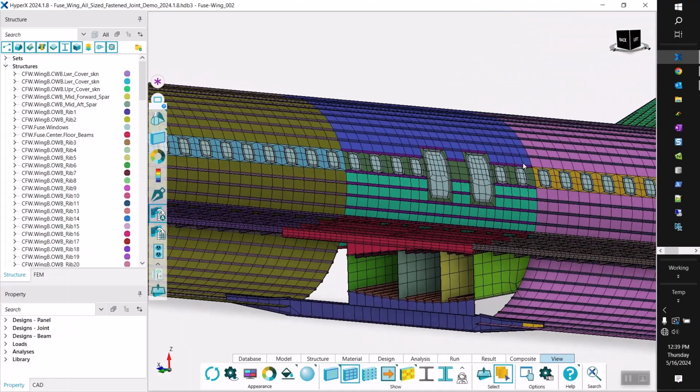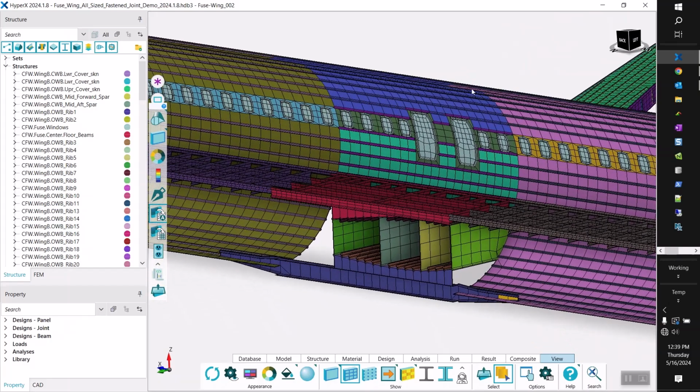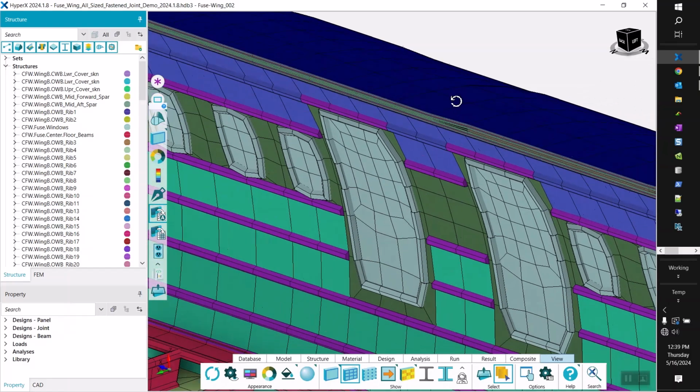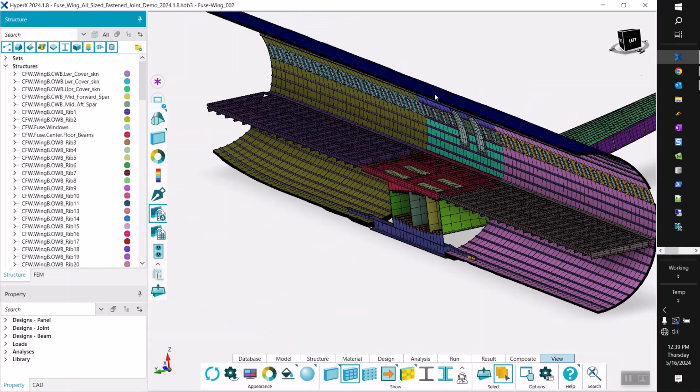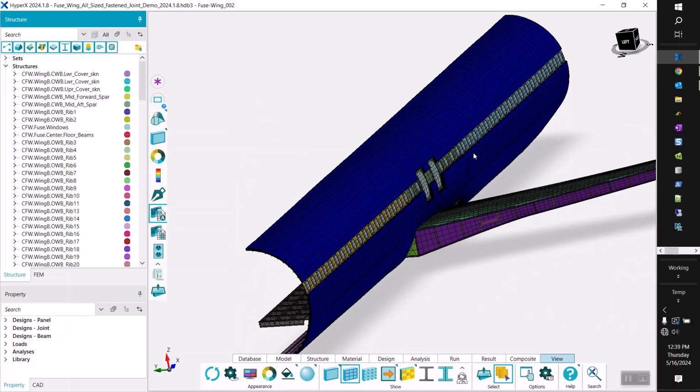And what I need to do is create an entity called a joint at these locations. But just so we're all on the same page here, these would be edge of structure boundaries and would indicate locations where, let's say if you had plies, that your plies are not contiguous or not continuous across that boundary.